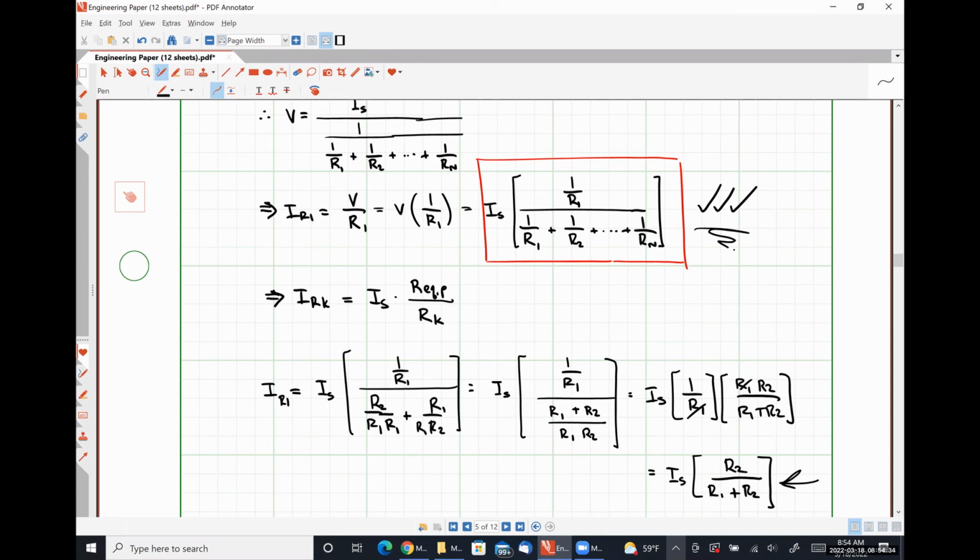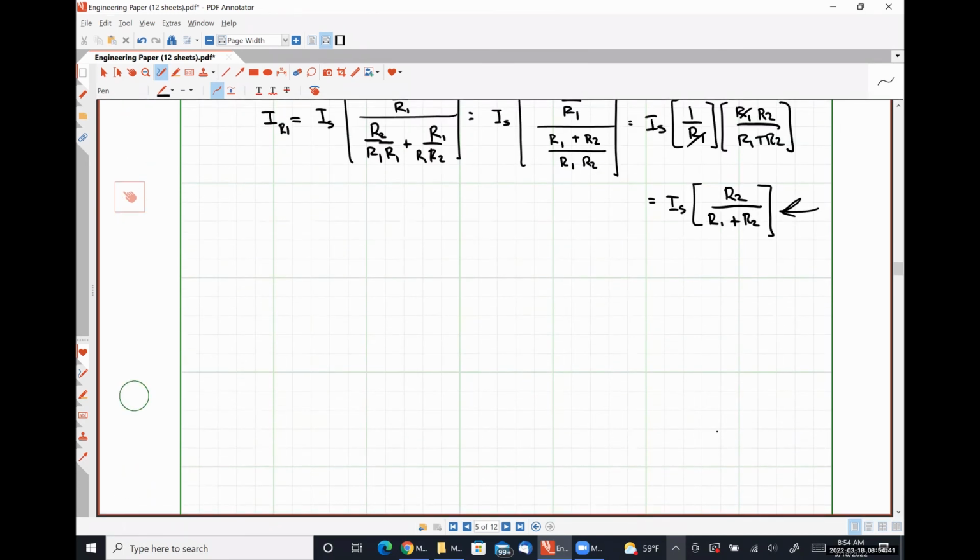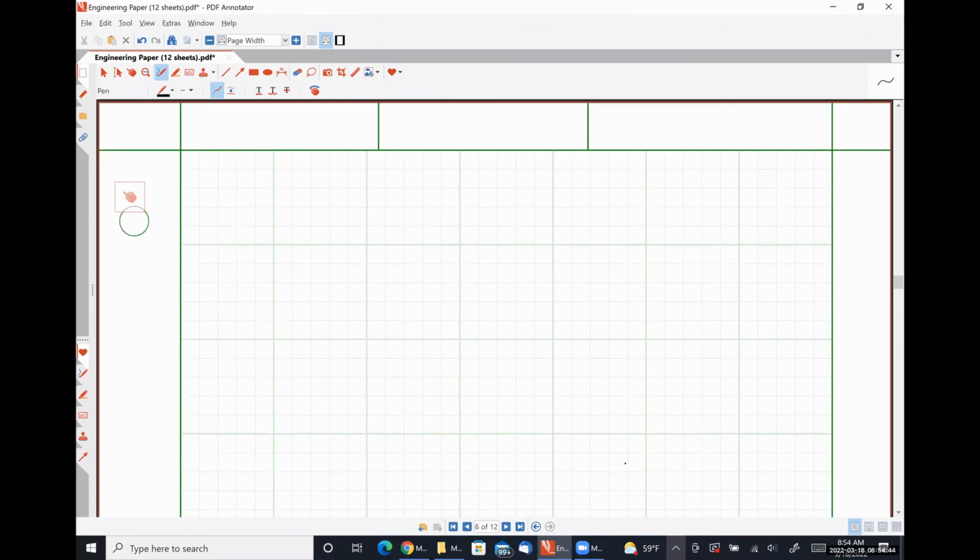All right, let's work an example problem or two involving current division just real quick, and then I'll be finished talking. So let's say we have a 5-amp source connected in parallel to a 2-ohm resistor and connected in parallel to a 6-ohm resistor. And I want the current that I'm going to call I6.